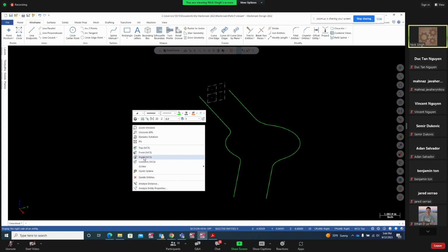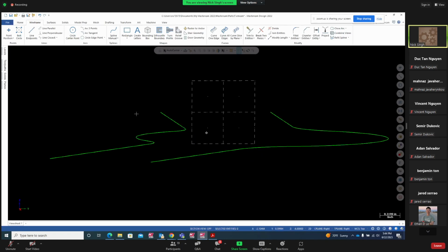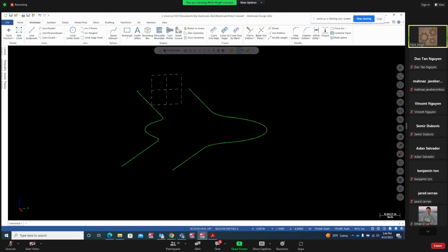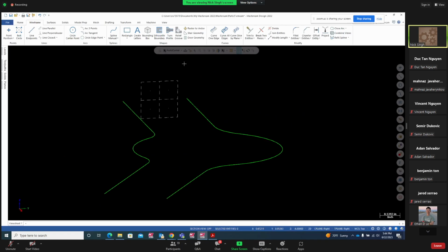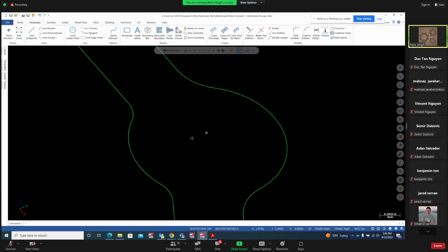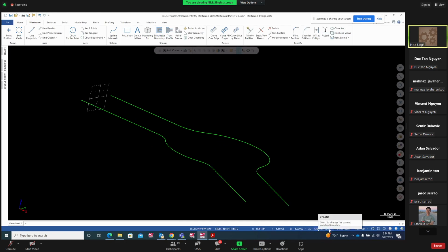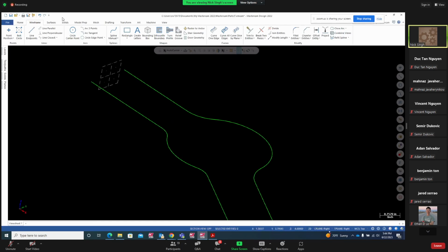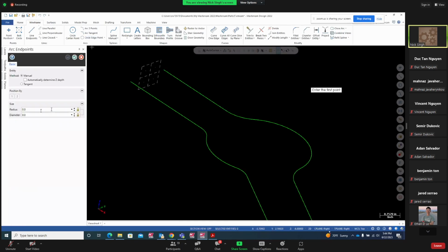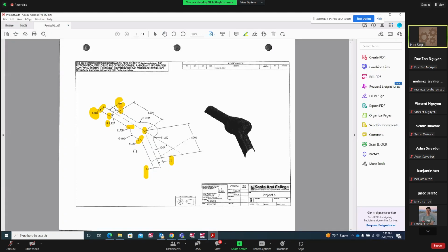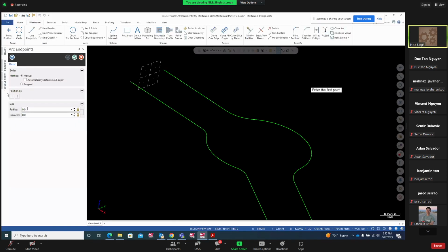You can go construction plane right if you want to see that, but I'll just use my mouse and stay over here somewhere. Yes, I'm in right plane now. Look at this construction plane right. Z is minus 6. All right. So go to wireframe, create arc endpoints right here. And the radius of the arc is 1 inch. So I'll put this radius 1 inch.